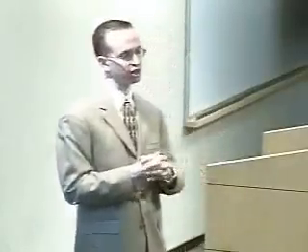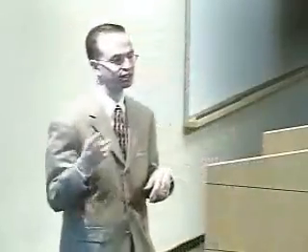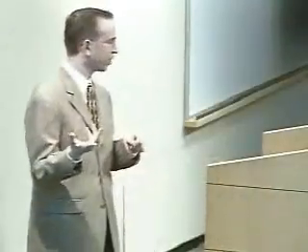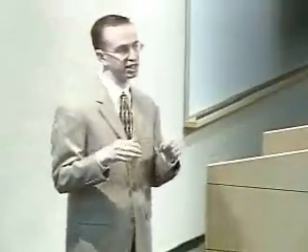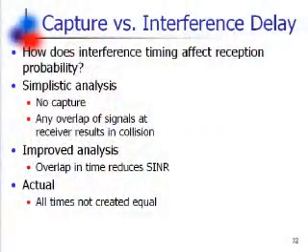So the takeaway here is that, again, the off-channel interference looks good for cramming in more channels, but the off-channel reception looked questionable. Certainly, if one were going to try to leverage this in a protocol, one would have to take into account the fact that it's not working so well for anything other than 1 megabit per second. And the higher-level result is that the emulator allowed us to characterize this sort of behavior in a very fine-grained fashion, and allowed us to gain insight that would be difficult to gain otherwise.